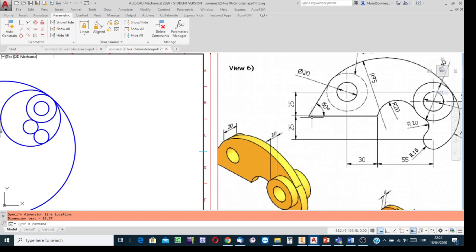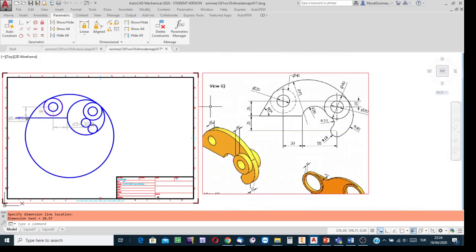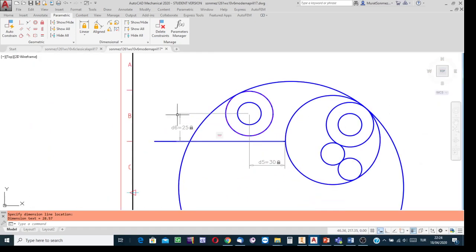And the last trick: input the inclination angle as measured with respect to a horizontal line which passes through the tangent point in the counterclockwise direction. The angle has been calculated and measured, and so correspondingly input in the counterclockwise direction. These are the tricks.